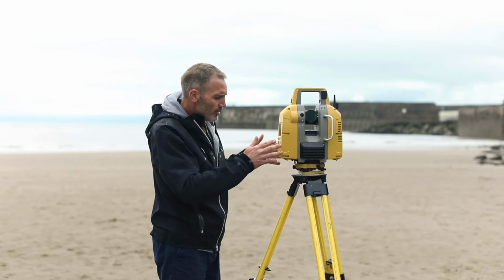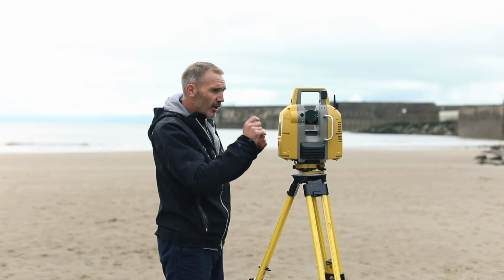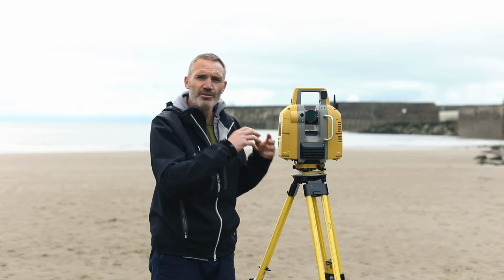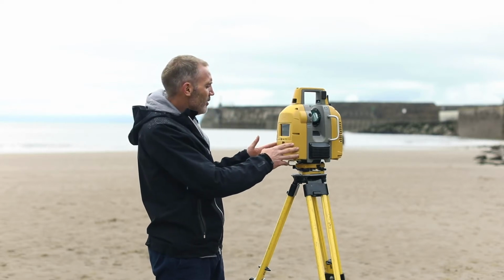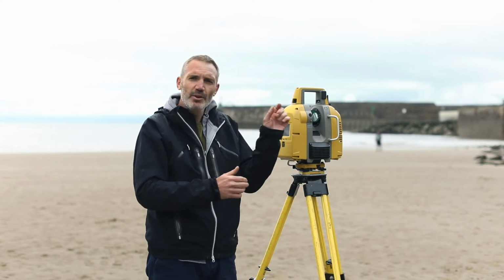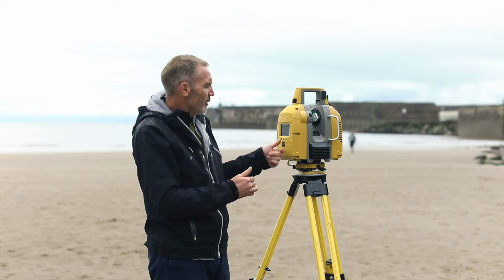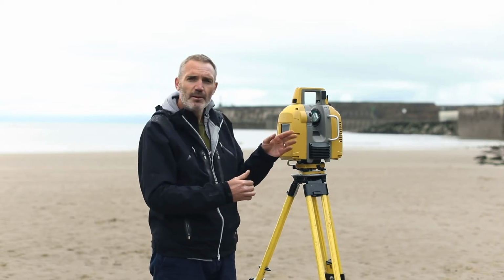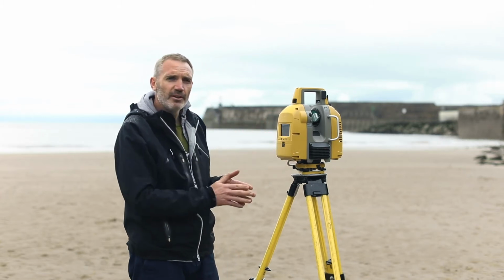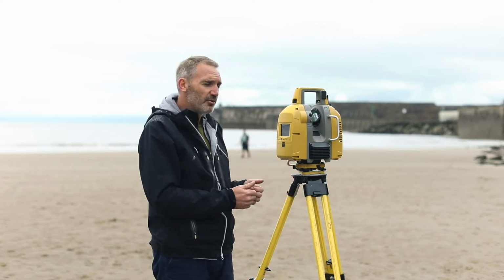So, set up on the point, decide on the parameters for the survey, and that is the density of the points. We don't want to capture too many data points, and the density is expressed on the instrument in terms of the spacing between the points at a distance of 10 meters. At the moment it's set for about 3 millimeters at 10 meters. That's probably still a bit of an overkill for this data set, so we could open it up and that would speed up the actual survey time.